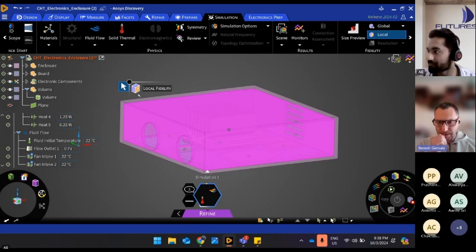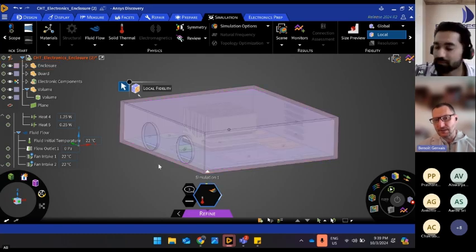What would be an application? For example, cooling of MOSFETs or hot chips, like vapor chambers or heat pipes. Yeah, heat pipes traditionally are modeled using general conduction values. You can use isotropic conduction values for heat pipes, but modeling the two-phase inside a heat pipe is traditionally not something that most thermal analysts will do.